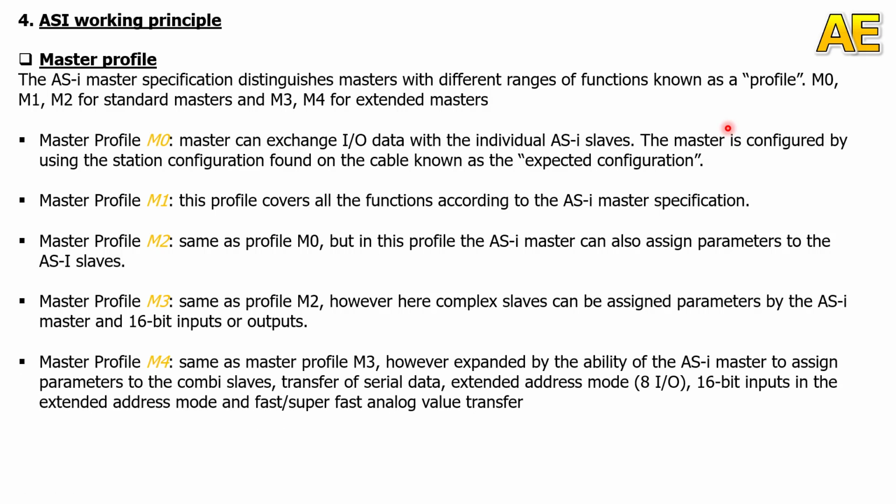And the final one, M4. Same as master profile M3, however, expanded by the ability of the AS-i master to assign parameters to the combined slaves, transfer of serial data, extended addressing mode, 16-bit input in the extended addressing mode, and fast or super fast analog value transfer.